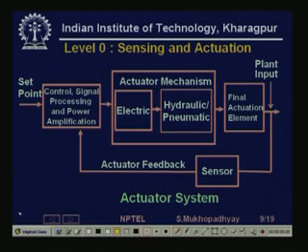Actuators, as I said, take the logical input from the controller and convert it to a physical plant input. That is what they do. Now obviously, what is necessary for this? There is variable conversion necessary, and one thing very much necessary is that these logical inputs are just logical, they do not have power, they have the information. So you have to do a lot of power amplification.